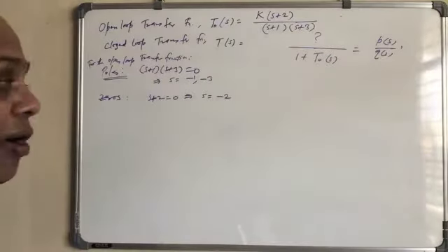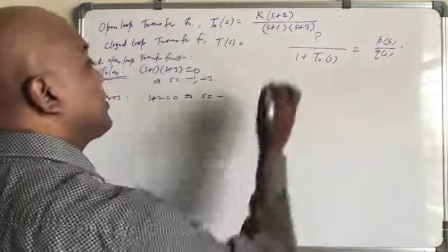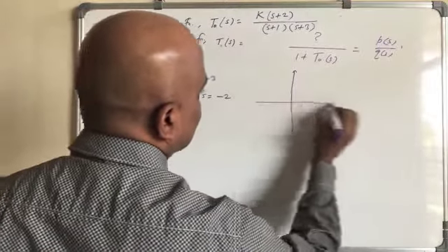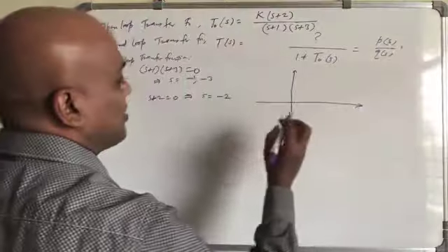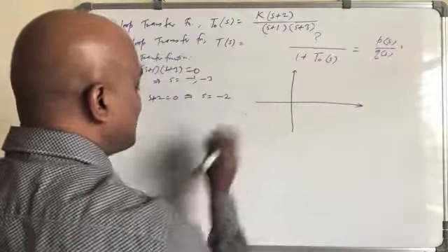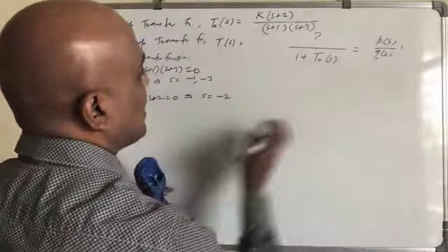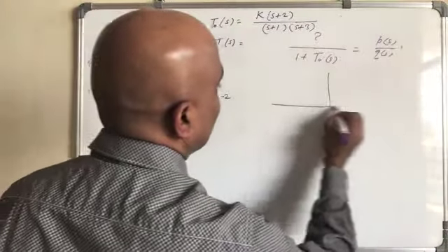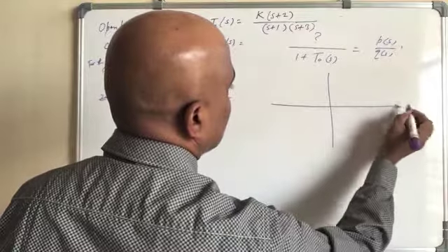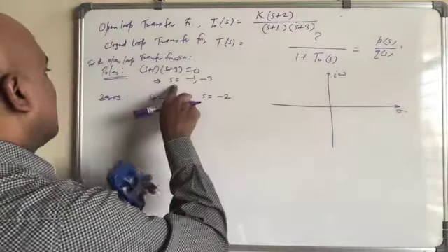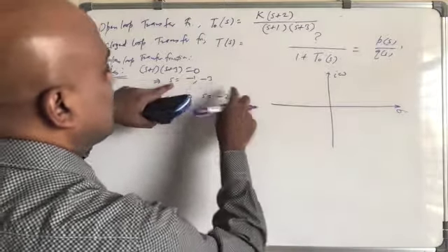Yeah, we got that. If you already know about root locus, then after you learn this chapter, you can plot it immediately based on this. How will you plot? You will do it like this. On the s plane, with sigma and j omega axes, poles you will denote as cross.